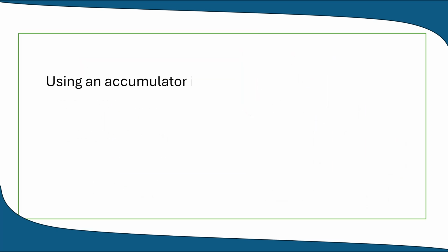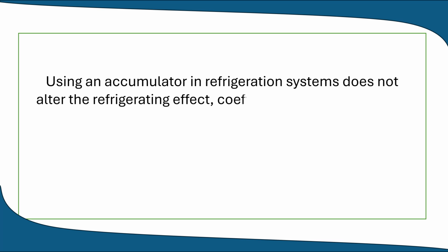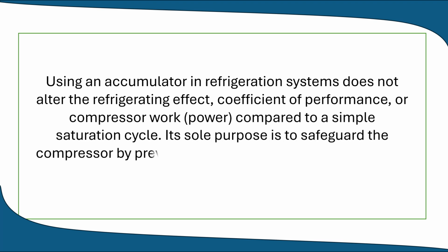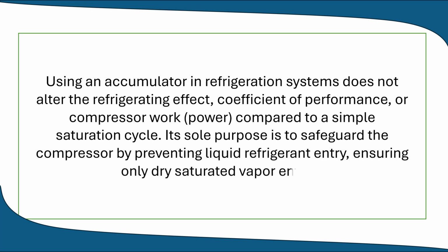Using an accumulator in refrigeration systems does not alter the refrigerating effect, coefficient of performance, or compressor work, power, compared to a simple saturation cycle. Its sole purpose is to safeguard the compressor by preventing liquid refrigerant entry, ensuring only dry saturated vapor enters.